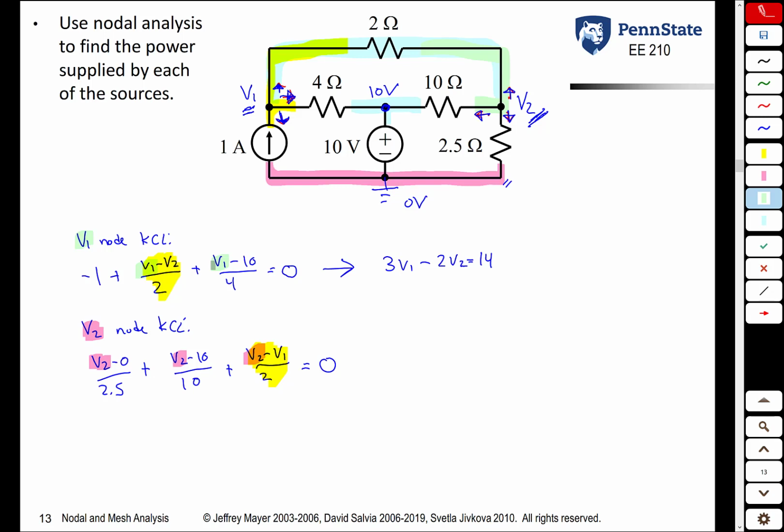So that's going to be the structure, if you're doing KCL and doing the currents leaving the node, it's always going to be that voltage minus the voltage on the other side of the resistor. In the other case, it's going to be V2 minus, V2 minus, V2 minus. If you sum the currents entering the node, guess what? You do not have that nice structure. That is one of the reasons why I like to sum the currents leaving the node.